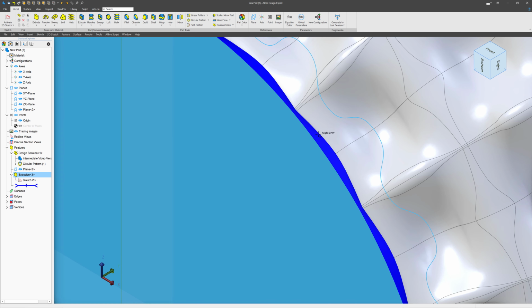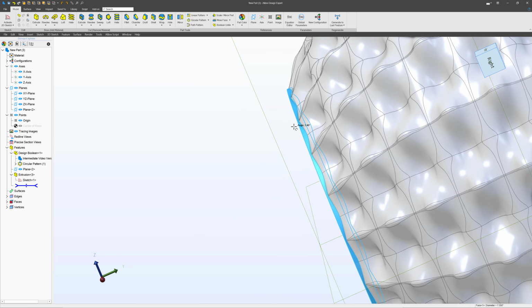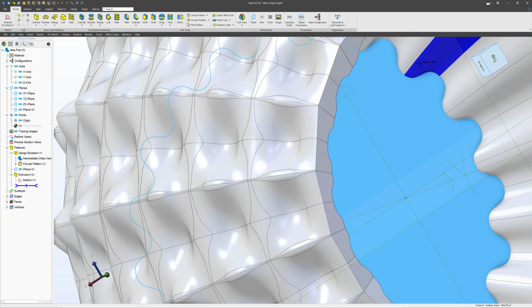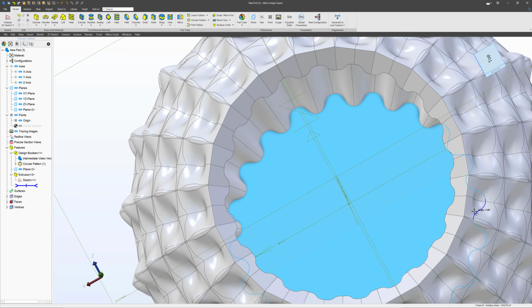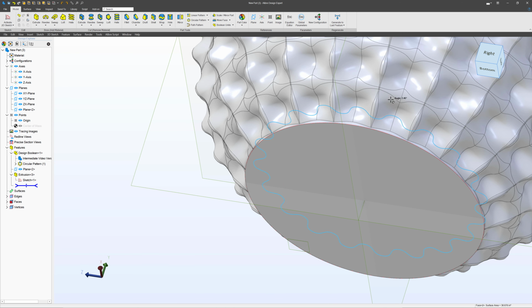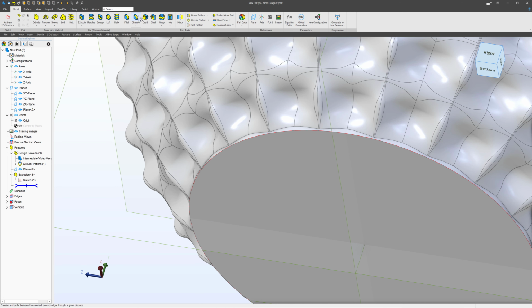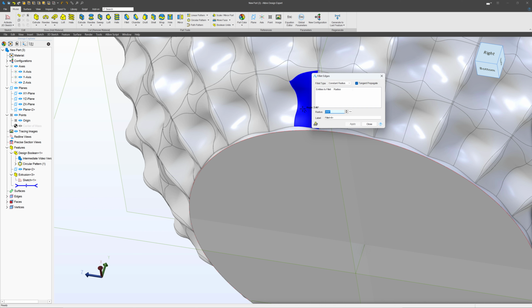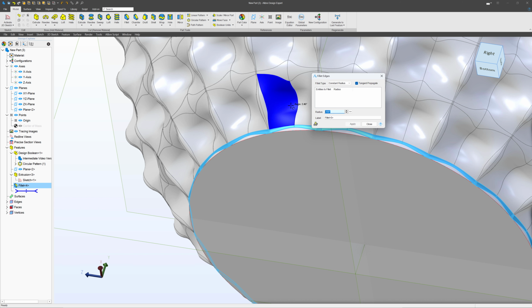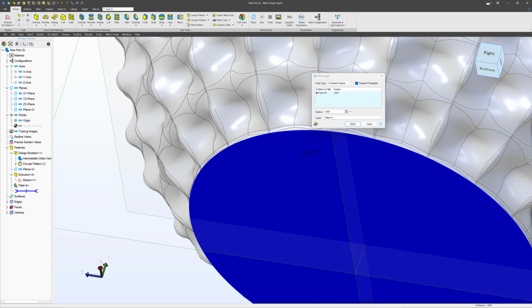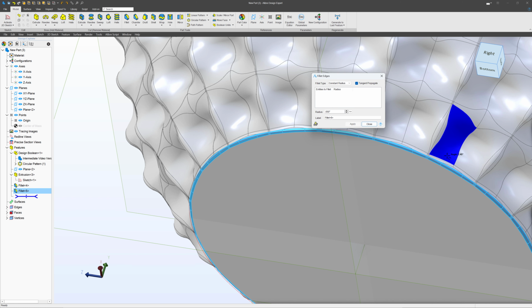And that's just enough that we got a little face on the outside there. And we have a complete face on the inside. So that's just about exactly what I want. I'm going to go ahead and just add a few other fillets. And I can start by giving, let's do a fillet of 0.1, let's say, and we'll go all the way around this face. And then apply that, we'll go half that, 0.05. And then we'll do this bottom face and apply that.